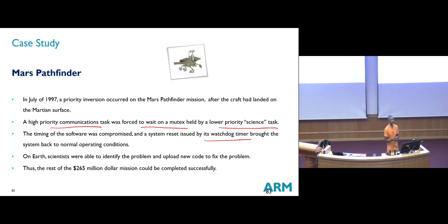A watchdog timer is a timer built into your processor that allows your system to reboot if it ever reaches some failure state that cannot be recovered from. For example, your phone. Sometimes you use your phone, then after a while it hangs and reboots by itself.